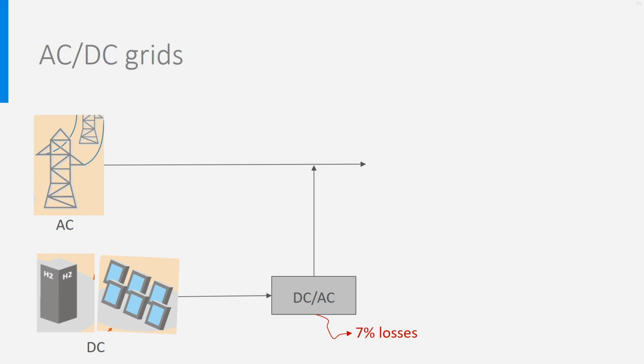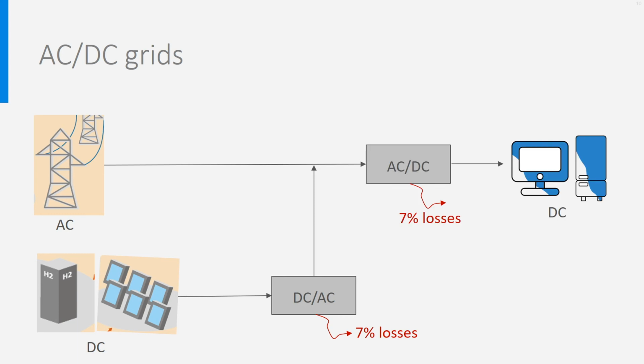Most home appliances, not all of them, but many of them, work on the basis of DC and are equipped with a converter that transforms AC to DC. This converter is placed in the product itself. Here too, there are around 7 to 10% losses. Using DC current directly in home appliances would therefore save energy, around 14%.